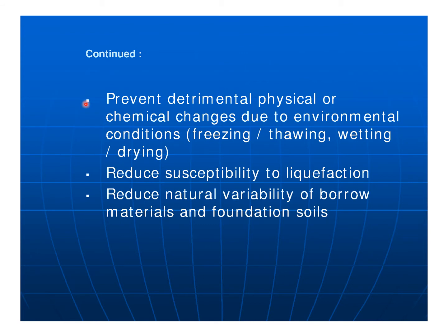Prevent detrimental physical or chemical changes due to environmental conditions: freezing, thawing, wetting and drying. Reduce susceptibility to liquefaction. Reduce natural variability of borrow material and foundation soils.